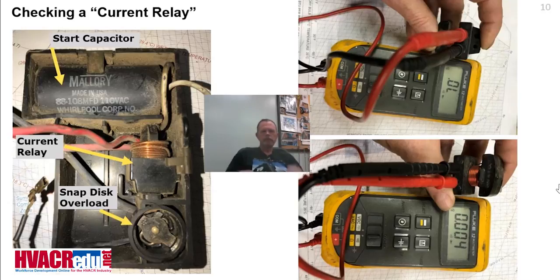Terry, what about measuring resistance across a de-energized switch? Are you sure? The loaded question for that, Terry, is is it a normally closed or a normally open switch? But we can go there in a bit. Ricardo, you said to replace a circuit breaker, should it be with higher capacity if the equivalent is not available? You're asking for trouble. Are you asking me if I should replace a 20 amp circuit breaker with a 30 amp circuit breaker?